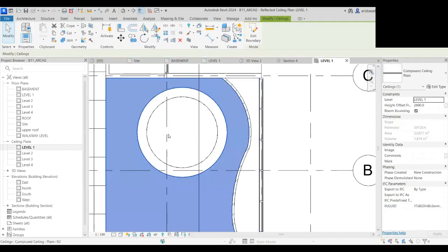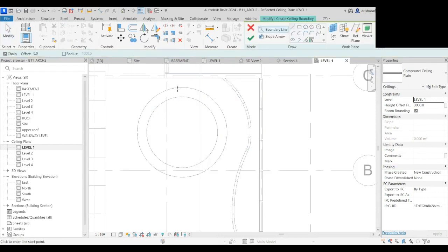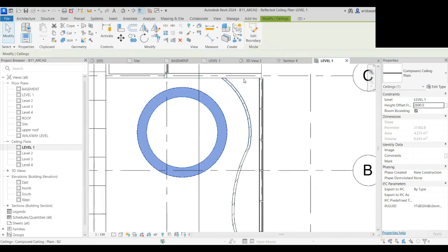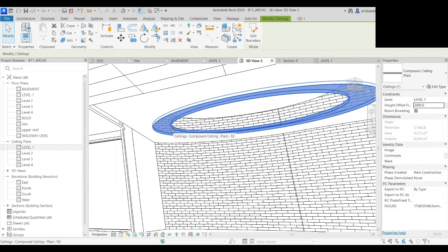Right click this, create similar, sketch ceiling, select this guy, this, and this, and that. So automatically now we are creating this. Okay, and then click check. We'll start at 2600. That's the lower part. Then we'll slope it up. Then click check. Okay. So now if you look at your 3D view, it's actually flat for now, right?